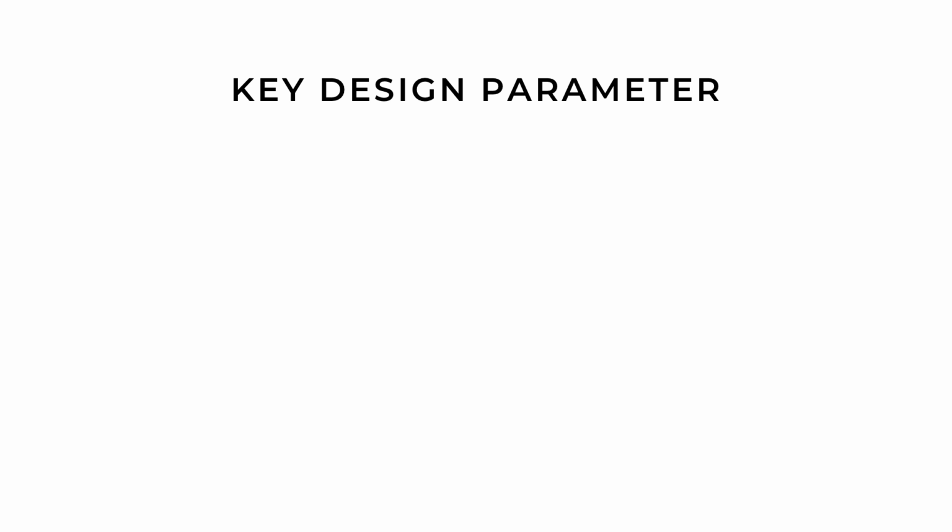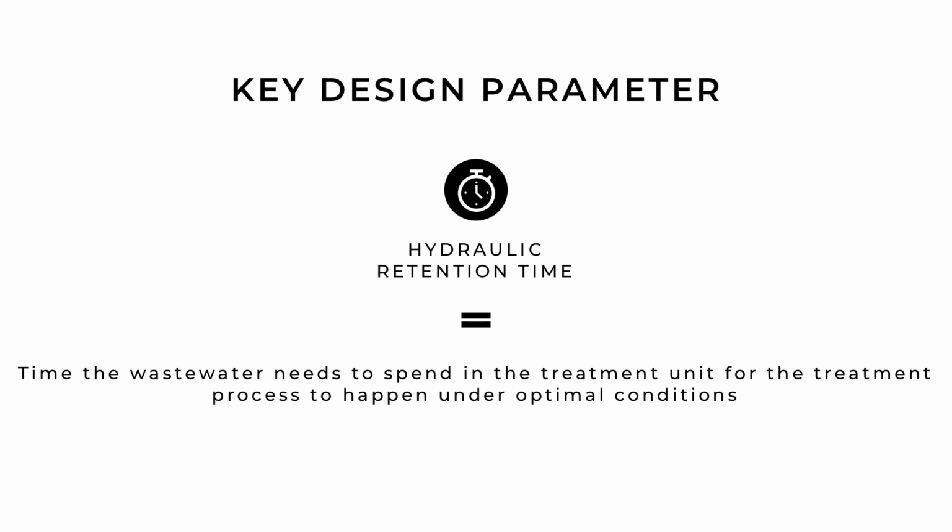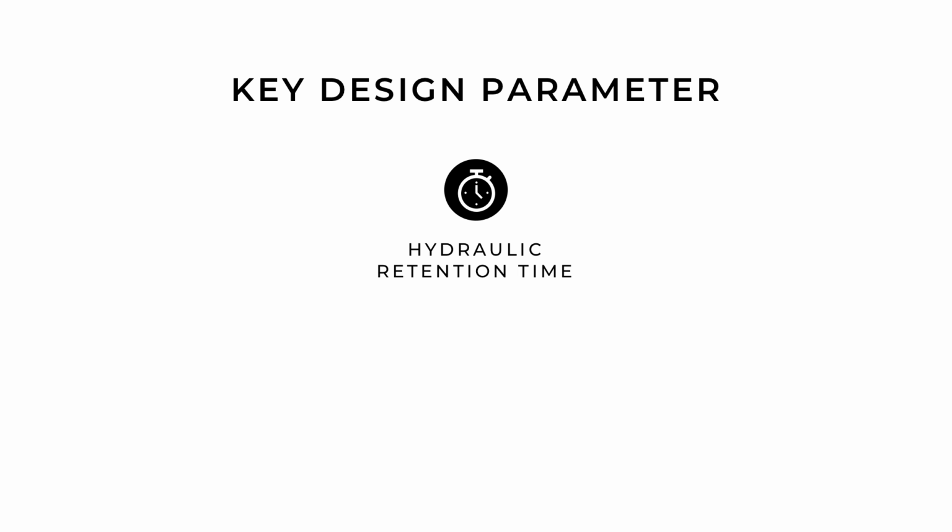Before I continue with principal treatment, I will briefly explain one key design parameter. This is the hydraulic retention time or detention time. The hydraulic retention time is the time that the wastewater needs to spend in the treatment unit for the treatment process to happen under optimal conditions. Let me give you an example.